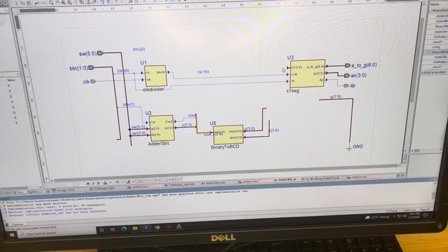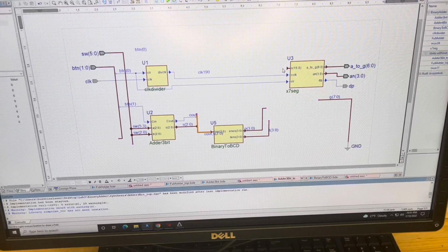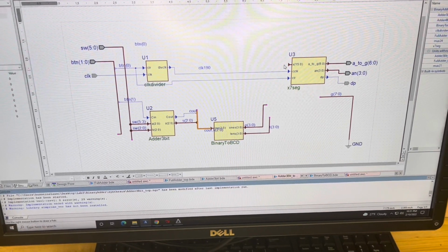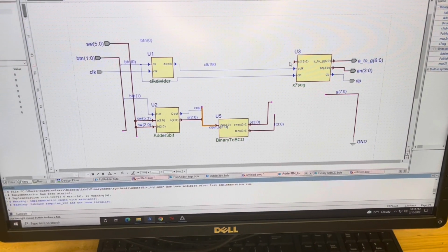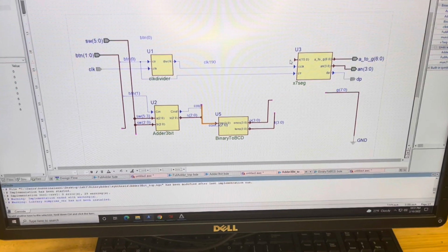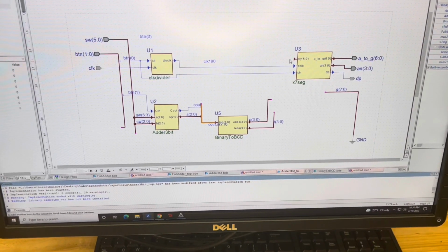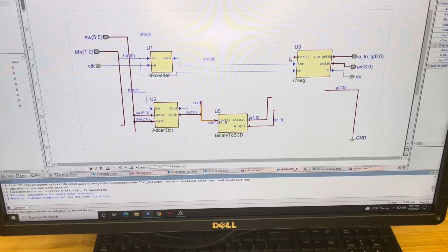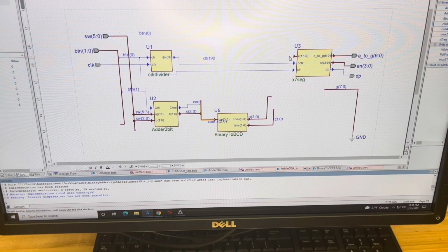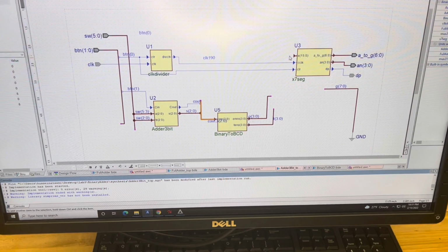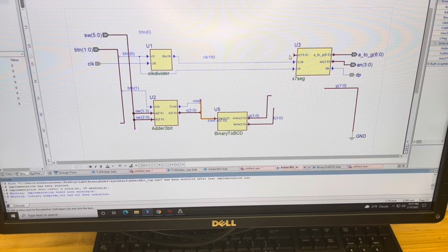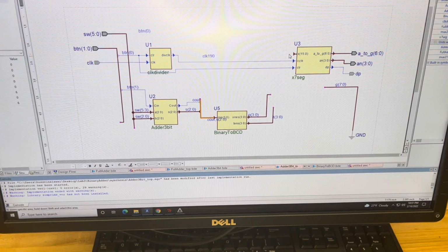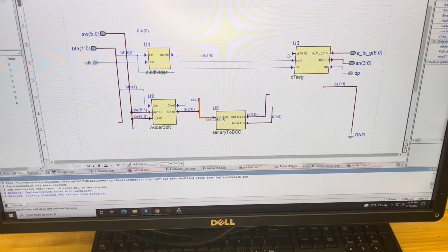Now let me show you how we could create the compound bus, which is the very complicated one. So I jumped ahead and used the harder circuit, because I want you to do it for the previous circuit that we didn't complete yet. First of all, you need to make all the buses that need to be connected to that compound bus. Give them names. Right now, as you can see, the ones, the tens, the ground, with the proper names, all of them.